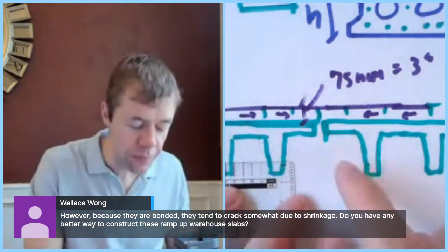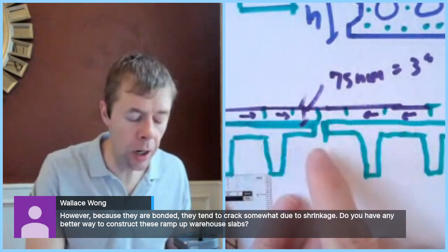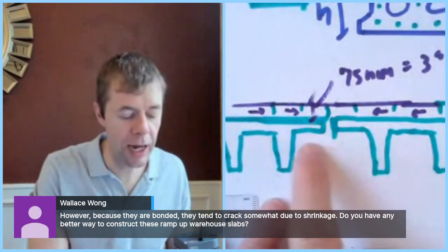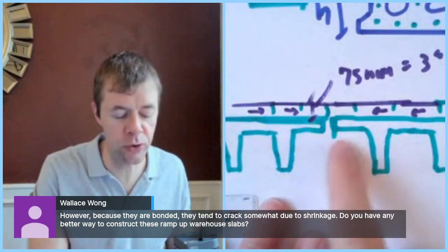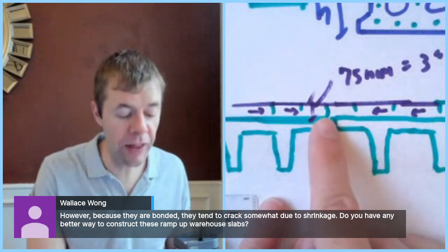They're awesome. So anyway, I would use fibers in this. If it's this type system, if it's this type of cracks, if the cracks are happening in between your two different structural systems, I would put extra reinforcing bar at that surface.